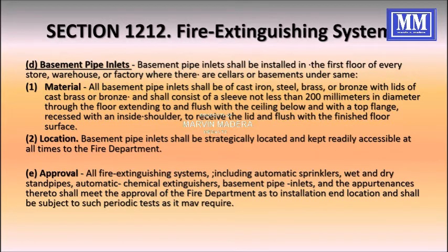Basement pipe inlets shall be strategically located and kept readily accessible at all times to the fire department. All fire extinguishing systems, including automatic sprinklers, wet and dry standpipes, automatic chemical extinguishers, basement pipe inlets, and the appurtenances thereto, shall meet the approval of the fire department as to installation and location and shall be subjected to such periodic tests as it may require.